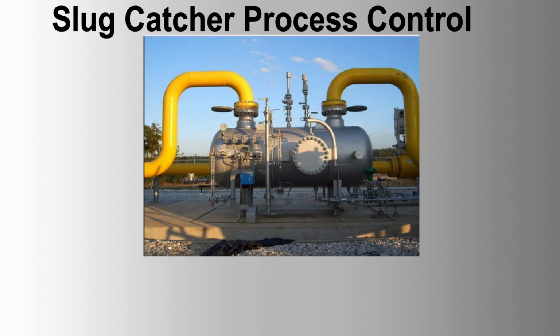Example control loops. 1. MPC loop for gas pressure. Input, gas pressure measurements, upstream pressure changes. Output, control signals for gas outlet valves. Optimization, minimize deviations from pressure set point while respecting constraints. 2. Adaptive control loop for liquid level. Input, liquid level measurements. Output, adjusted PID controller parameters for the level controller. Parameter estimation, continuous update of model parameters.